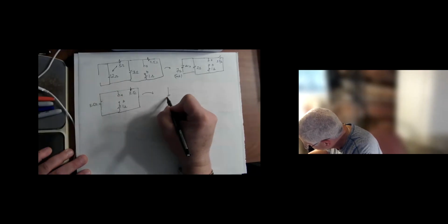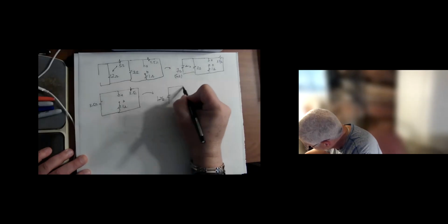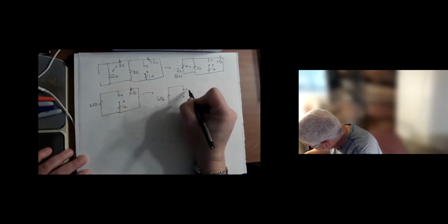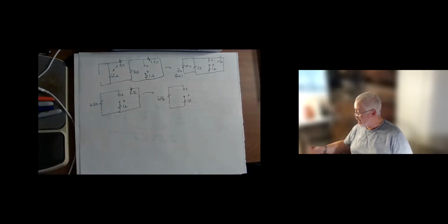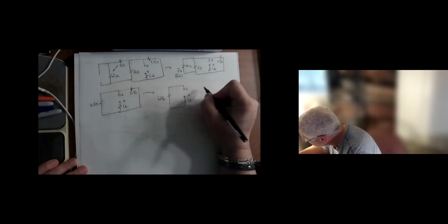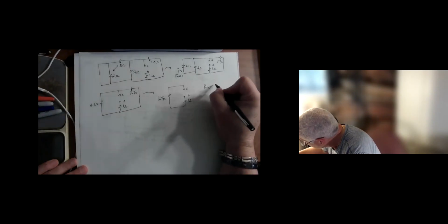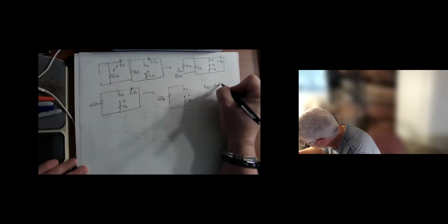You can see that these 3.5 ohm resistors are actually in parallel, so we combine them in parallel. Then we have 1.25 ohm, with A and B. And now you can clearly see these two are in series. So RTH is equal to 2.25.